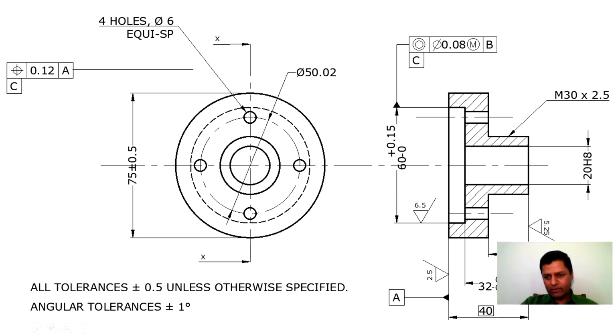Some special dimension properties like here and here. How to get the leader line up here, also here. How to show the phantom line and the arrows for the sectional view. How to show the geometrical tolerances, you can see it here and here. How to write the dimension notes in the drawing. Some special instructions you can write using this kind of notes using the multi-line text.